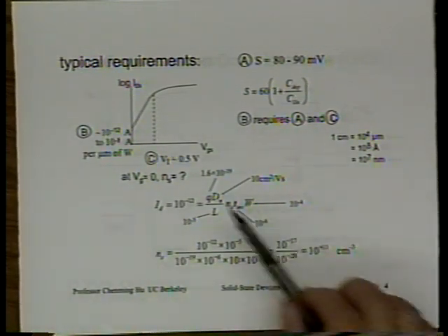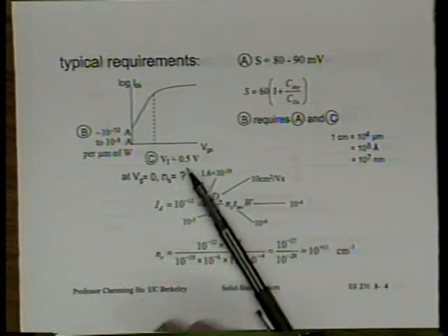One thing is that the technologies will provide several different kinds of transistors in a given technology with different VTs. So let's say all the transistors will, shall we say, be designed with the high VT transistor, let's say 0.5 volt. So you have designed this circuit now. As a result, leakage current is very low. Is that right?